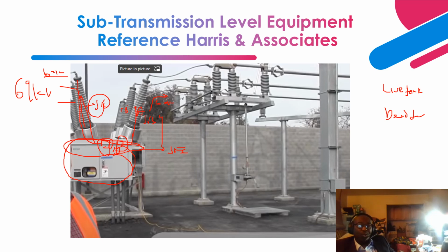And I explained to you, this is a porcelain type of external bushing, external insulator. For these external insulators, we have two types: the porcelain and the polymer. The porcelain is made from pottery material, clay material, and it is very rigid. In one of my presentations, I explained the differences between the two types of technology, the two types of materials, porcelain and polymer.